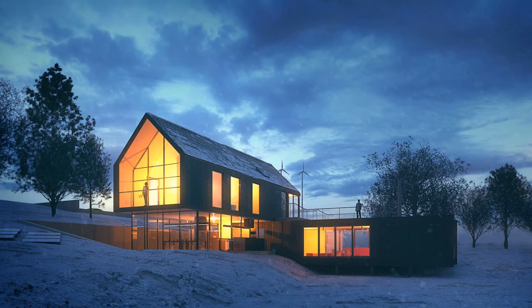And that dome light is set to be a winter sky, low light condition, and I believe the intensity value is set at 15, and so that's effectively what we've done to get that low light in the exterior and then nice bright lights in the interior using exposure value tweaks. And then finally we've rendered this in passes, and I'll show you how you can export individual parts of this frame out to Photoshop.